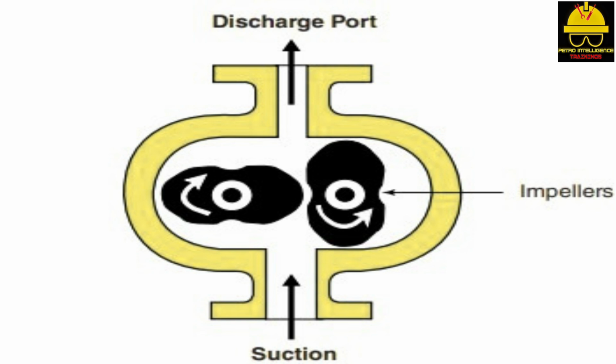The design clearances on the internal lobes of a lobe compressor allow some slip. The slip is aggravated at high discharge pressure when low-density gases are being pushed. Process slip is constant only when system pressure is constant. Lobe compressors are designed to have constant volume discharge pressures and constant speed drivers. Lobe compressors do not use discharge or suction valves because they are not designed to operate at a specific pressure. Discharge pressures are determined by the system's process pressure.